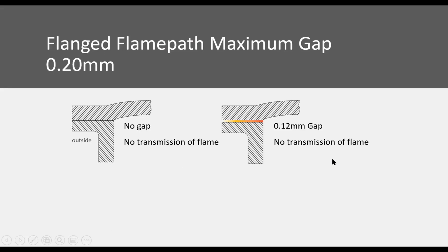If the gap was only 0.12, it is still within the maximum gap, there would still be no transmission of flame. It will be cooled and will be losing its energy before it ignites the outside atmosphere.